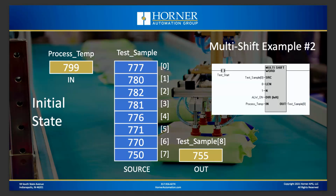So here's our second example where we've assigned another multi-shift function. This time, our data type happens to be word data type. In this case, we're talking integers. Our source is another variable array called test_sample. It also happens to have 8 elements in it because it's easy to show on the screen. If you get more than 8, I can't really draw diagrams very easily. Again, we're going to shift by 1, which is what we do most of the time.